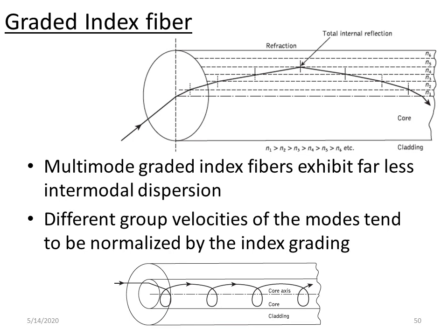But in the case of step index fiber, what will happen? Within the core there is a uniform refractive index, so whichever ray passes through the center reaches first, and whichever ray passes near the cladding reaches after the center ray. So there is a group velocity difference, and pulse broadening or pulse spreading takes place within the optical fiber. That's why dispersion is more in the case of step index fiber, and it is less in the case of graded index multi-mode fiber.